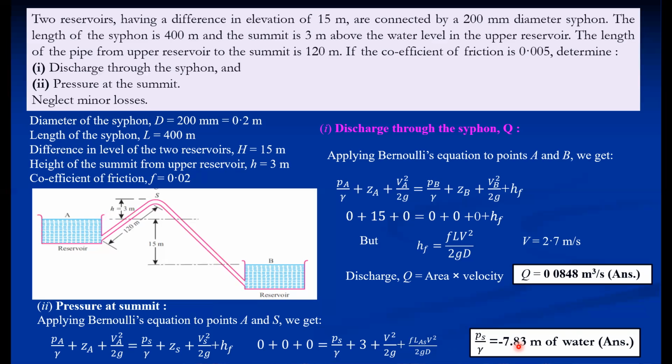So this is the way we can solve the numericals. There are many cases, but every time you have to apply Bernoulli's equation only twice. In most of the cases, we start by applying Bernoulli's equation between A and B. If not possible, you can choose this one. Almost all relevant information is given. So the analysis of a siphon means we have to apply Bernoulli's equation twice. That's it. Remember this, and you won't find it difficult to solve problems on siphon, of any kind.